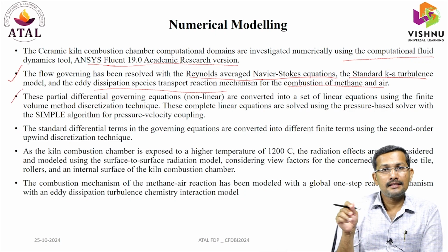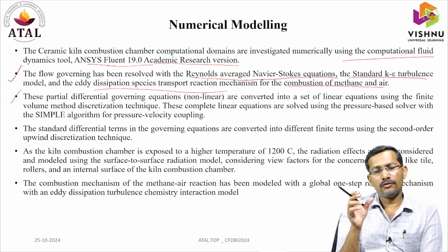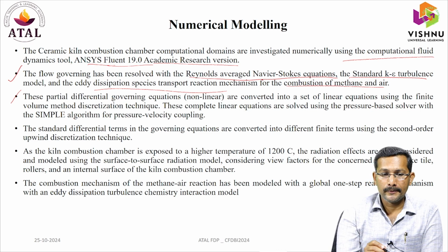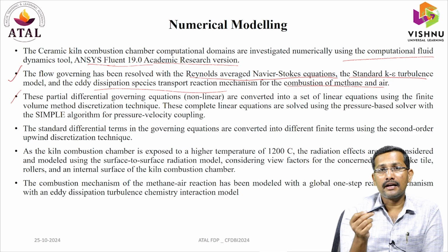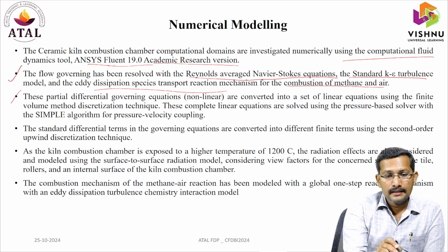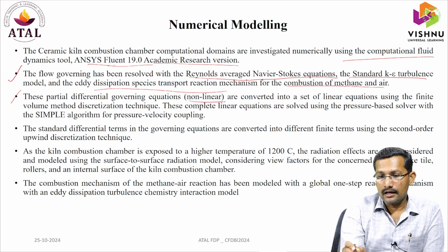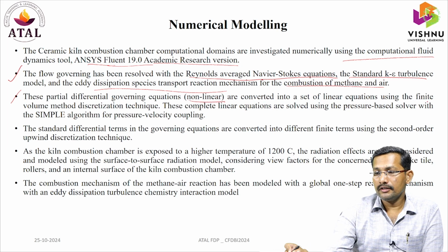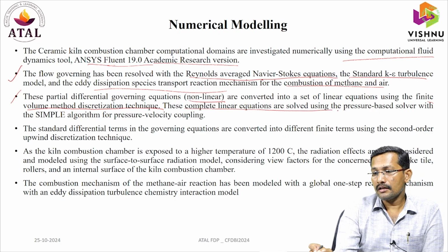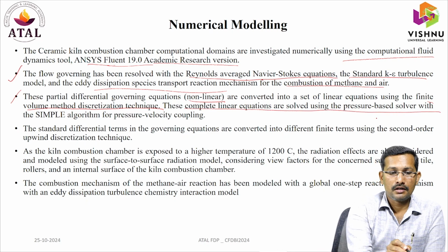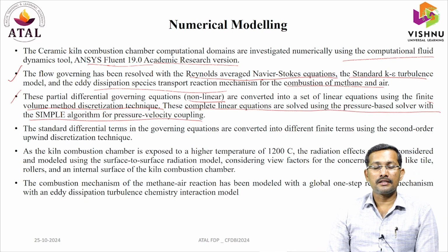Now, using all these governing equations, we are going to use the finite volume method. I am telling what is happening exactly in that tool in the background. These nonlinear partial differential governing equations are converted into a set of linear equations using the finite volume method discretization technique. These linear equations are solved using the pressure-based solver with the SIMPLE algorithm for pressure-velocity coupling.